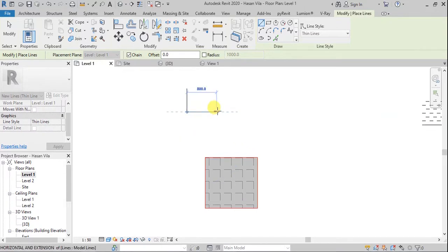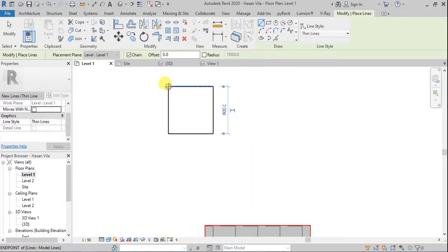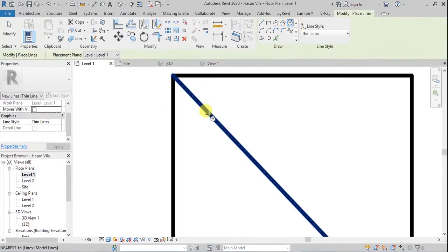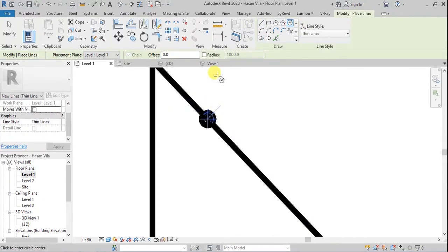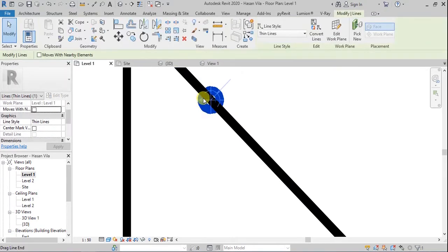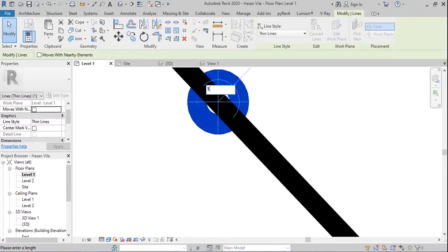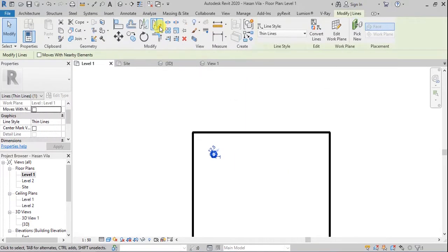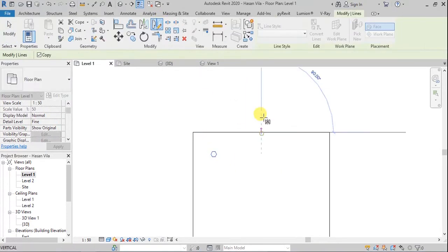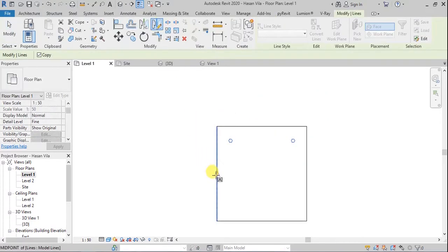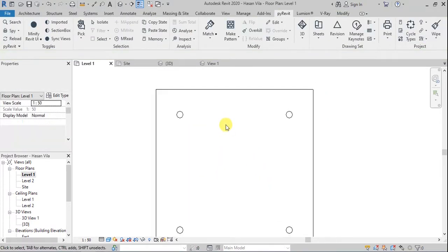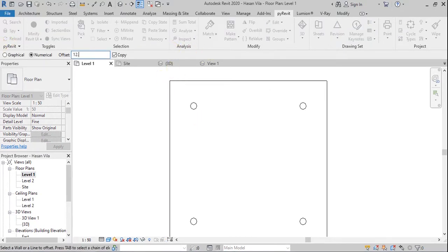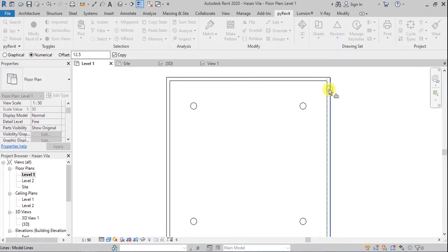Now let's create another hatch pattern similarly. Okay, this one is going to be the clear face concrete pattern. Here's the hole, 12.5 mm. Okay, mirror this circle. Okay, mirror this both. Here is my pattern almost ready. Now I need the gap between these 12.5 millimeter sets.